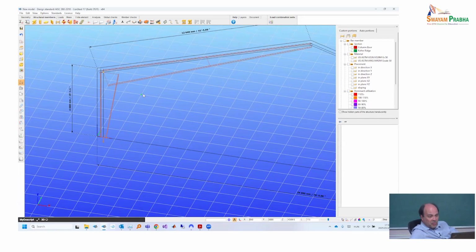Now, what are the out of plane supports for these structures? Typically, there can be a lot of things, but typically wall and roof purlins, so the point where these are attached. Of course, here we assume that those purlins cannot move along their length because they are somehow connected to some bracing, to some roof diaphragm or something.